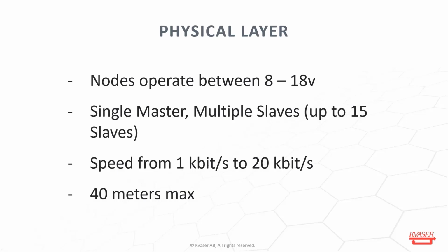The way you see a lot of LIN systems work as well is that they're part of a larger system. So that master and slaves, roughly 10 to 15 nodes, might connect into a larger bus. So you'll see the LIN, what's known as a LIN cluster, plug into a larger CAN bus. And then it communicates that up to a larger trunk.